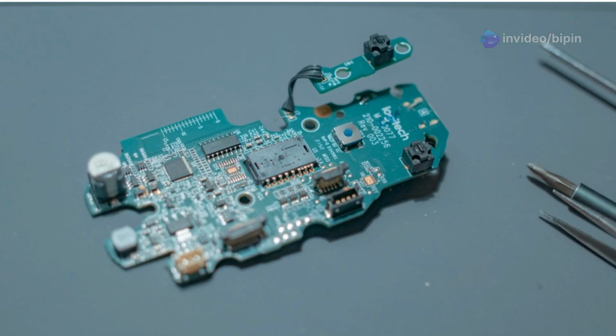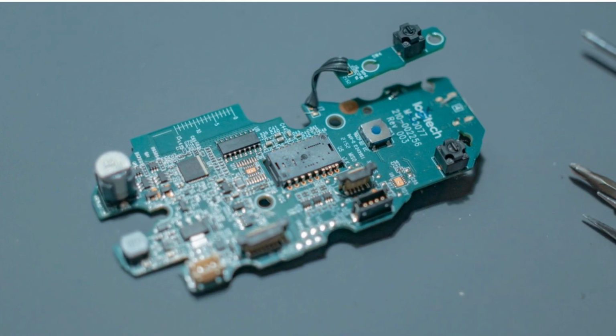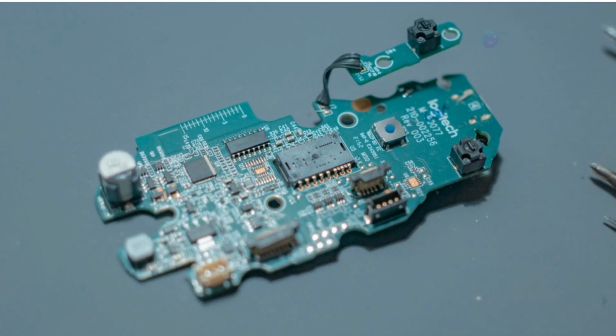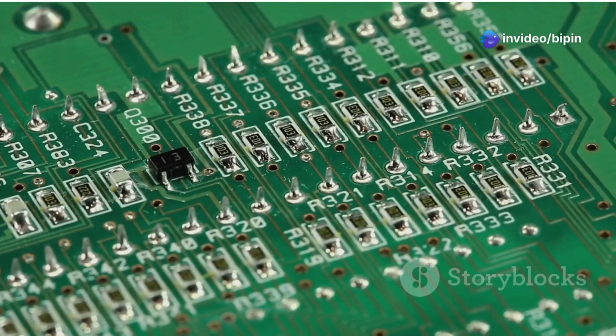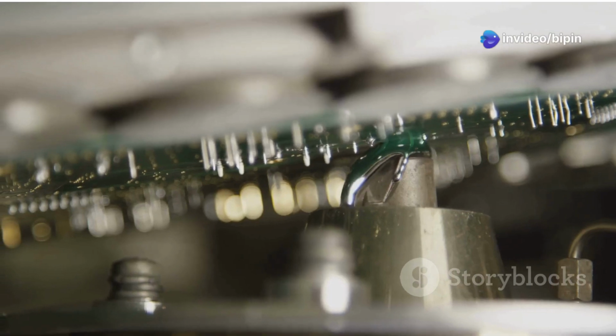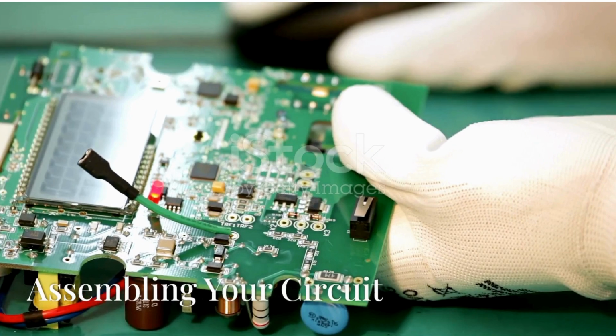Most manufacturers have online calculators that allow you to get an instant quote for your PCB based on its size, number of layers, and quantity. Choose a manufacturer that fits your budget and turnaround time requirements. Once you've selected a manufacturer, upload your Gerber files and place your order.